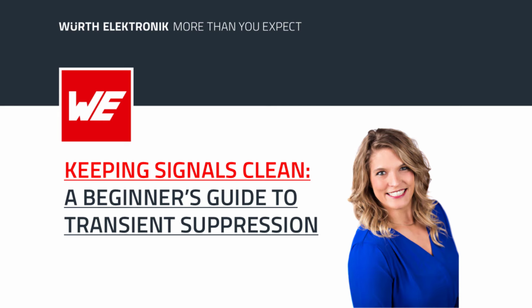Now, filter circuits are placed at the interfaces of the devices, and they not only attenuate high-frequency emissions and therefore maintain radio protection, but they also reduce transient overvoltage directly at the input of a device, so the functions of the devices are not impaired. Now, today's episode, we are talking about transient suppression at different interfaces.